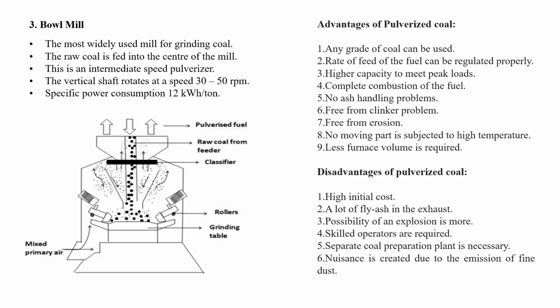So it is going to the 4 corners of the furnace: 4 outlets and 1 inlet, and then it is carried to all corners at a particular elevation. Suppose there are 6 mills, A, B, C, D, E, F. So there are 3 elevations of the furnace: AB elevation, CD elevation, EF elevation.